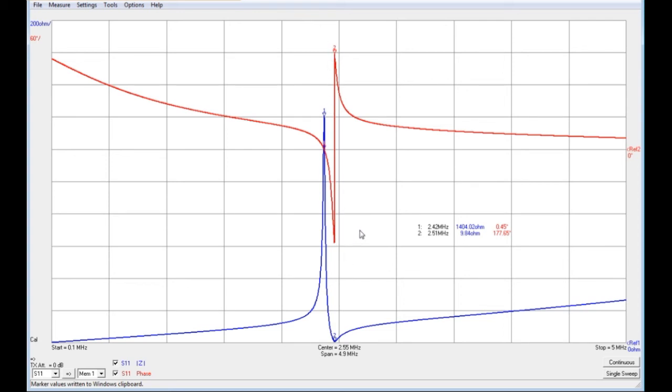As I've said in previous posts, that phase change position is very associated with wire length, and of course that's also reflected again through the primary. That's at 2.51 megahertz and is only 9.84 ohms at the bottom there. And this is very typical of both a cylindrical and a flat coil, a Tesla coil arrangement, where it's arranged as a loosely wound free resonator rather than a tightly wound voltage accumulator, as in a very tightly wound Tesla coil.